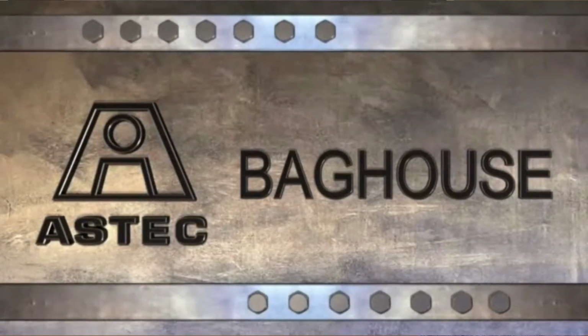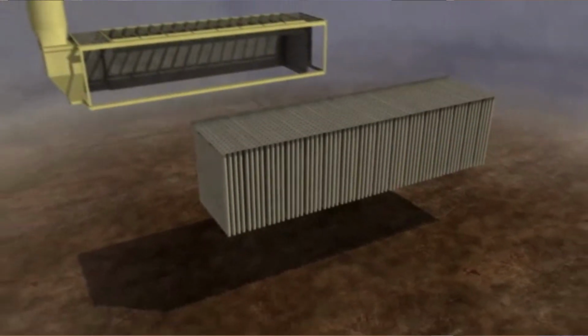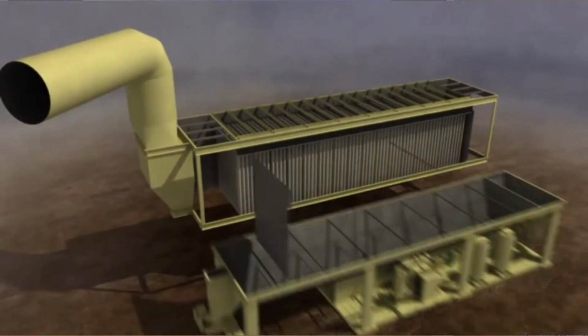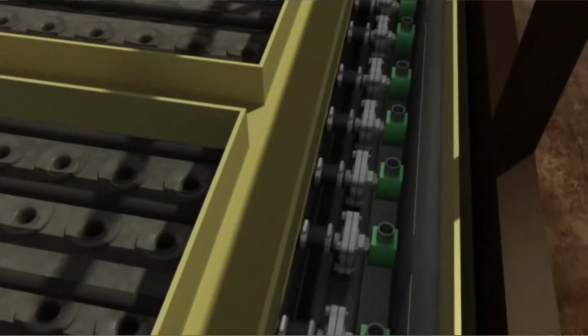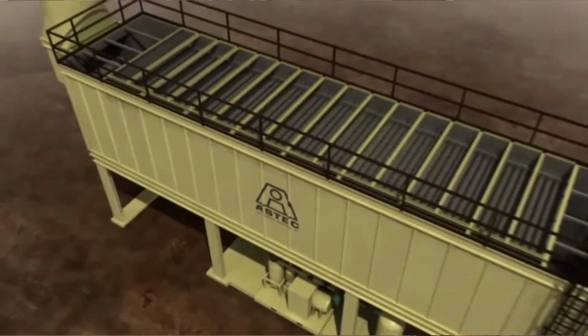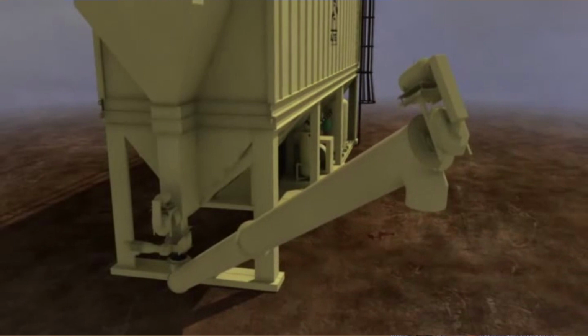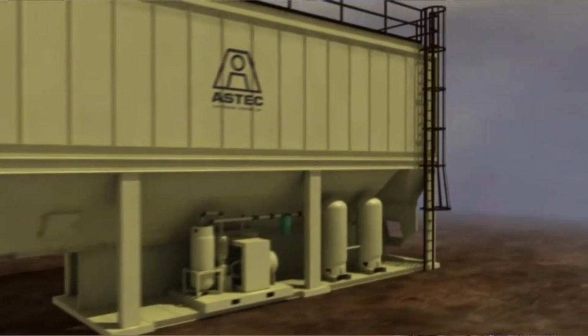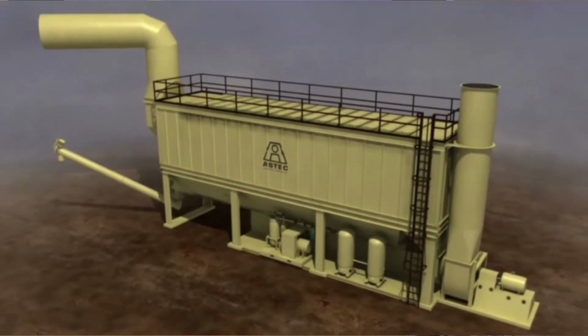So we're going to look at this animation of the baghouse. I'll try to narrate the dust coming through the system. Here's the tube sheet with all of your bags. According to capacity and CFM, the bag count will change. You will have to have extra modules for the larger capacity plants or if you're in higher elevation. These are the solenoids. This is actually where it's a pulse jet, so that means the plant air compressor is providing that air to shock those bags or to knock the dust off the bags. Here's your screw conveyor to convey it to the drum. And then as you see here, here's the exhaust fan that pulls up to the back side of the baghouse.